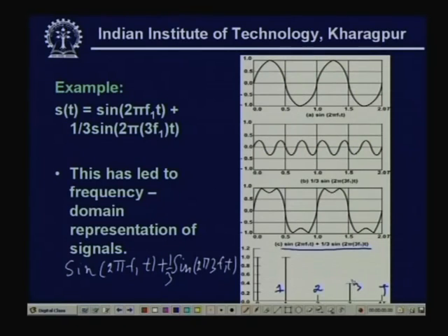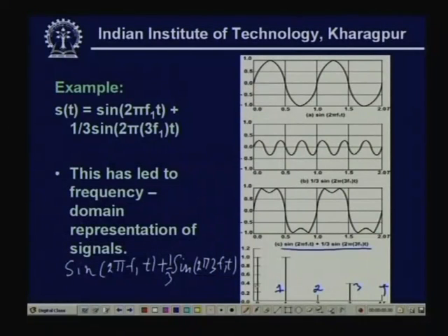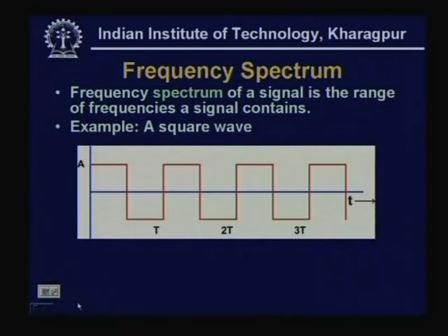So, you see, that waveform with 3 amplitude has got frequency 3 f1. How can we see this? This can be visualized with the help of a special equipment known as a spectrum analyzer. A spectrum analyzer is an equipment which can give us the frequency domain representation of the same signal. This frequency domain representation gives us information about the different frequency components the signal has got, which is sometimes very useful to us.